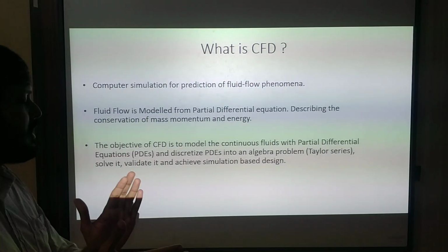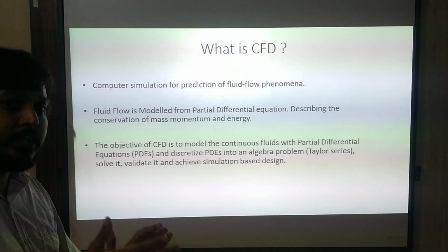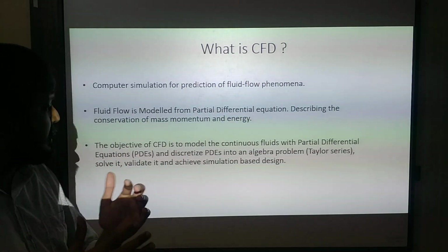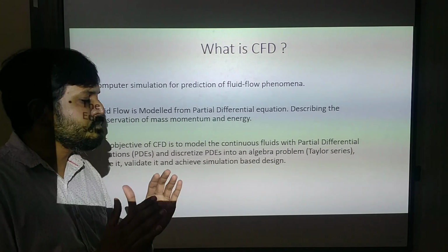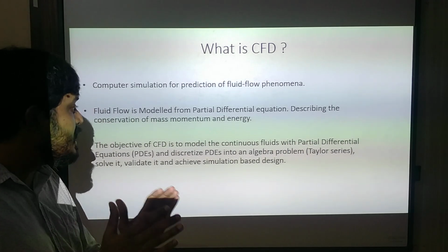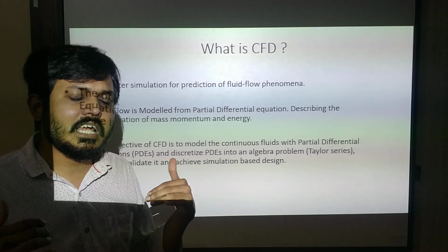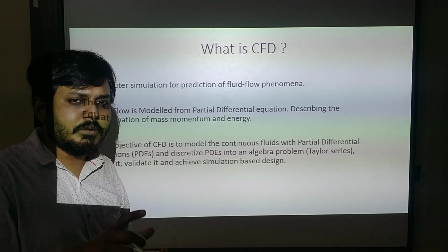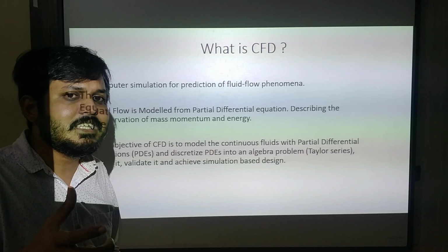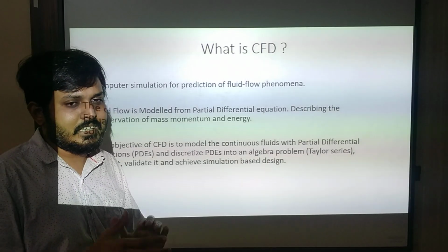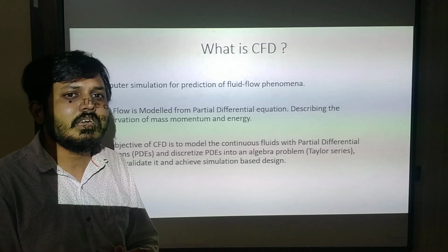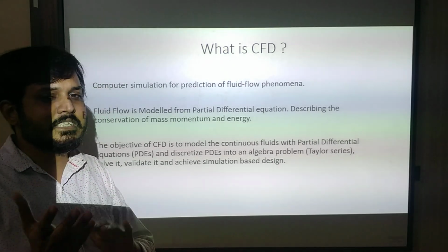So what is the objective of CFD? The objective of CFD is to model the continuous fluid with partial differential equations and discretize the partial differential equations into an algebraic problem. How do we discretize this? Using Taylor series expansion, which I think you have studied in your lower classes in mathematics, like f of x plus delta h.